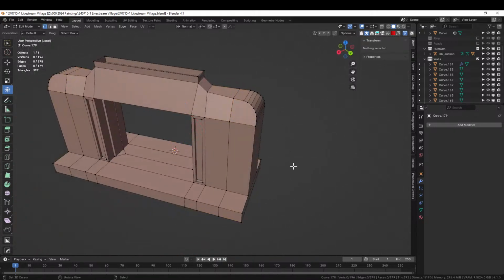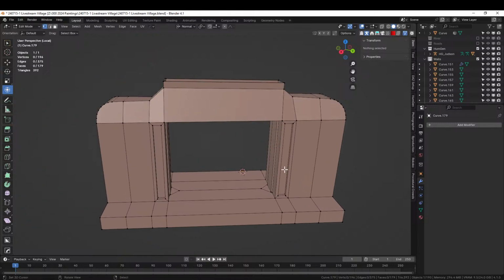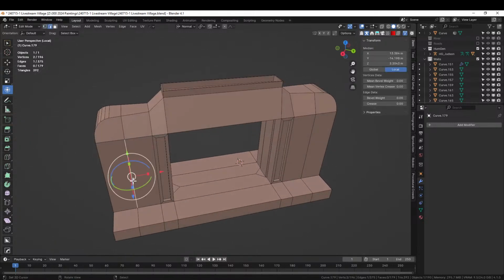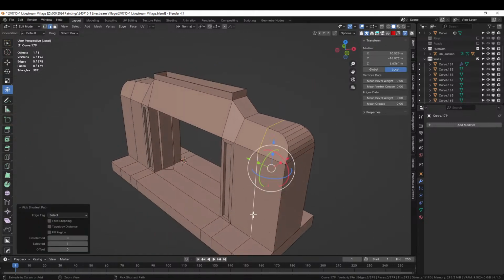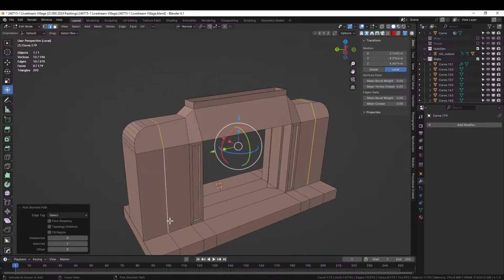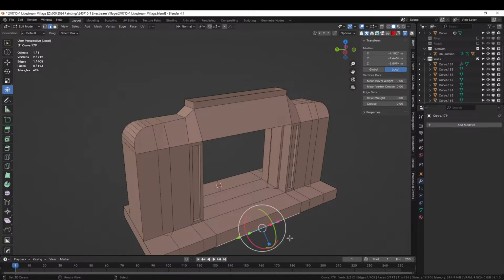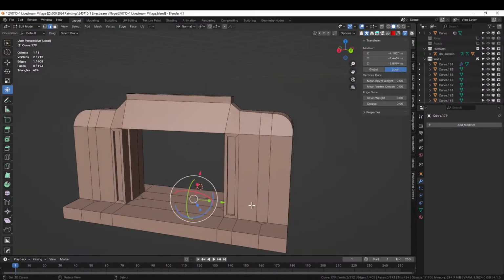Okay, so we've cut a loop cut both directions, both sides. So now we should be able to go, let's grab those to here. Yeah, just like that. And then this to here. Control bevel. Two pipes should be good. Okay. 2.